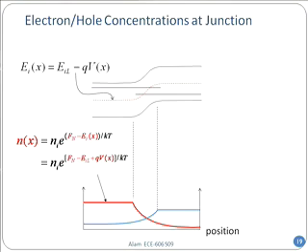But Ei, well, as the potential is varying across the junction, Ei should follow along. So Ei will have a reference Ei sub L, which is whatever Ei is at the left-hand contact, and whatever the potential does, Ei does the same thing. So you put it in there, and that's the second expression. So the only x dependence is coming through the potential V(x).